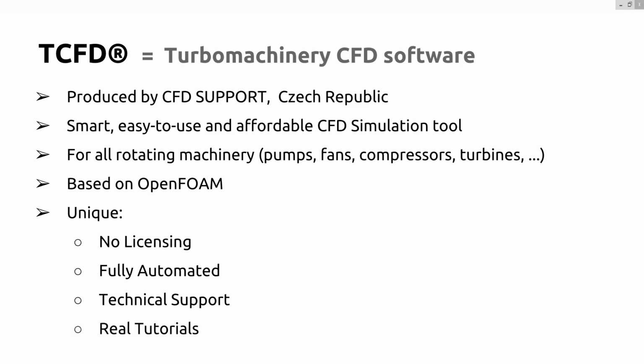And the last one would be that real tutorials are included in turbo machinery CFD, so the TCFD user has no doubts about the best practice settings. There are included real machines that are already preset. So the user can basically take one of those tutorials, replace the geometry and the physical data and settings, and run the simulation. The rest of the workflow is automated, so the requirements on the user's CFD skills are quite low.